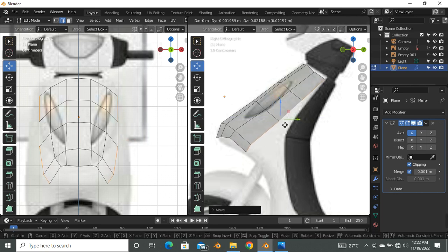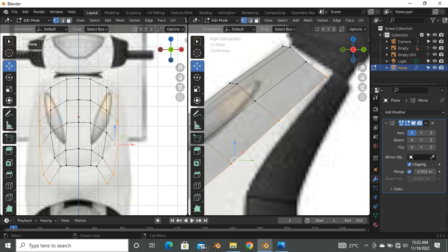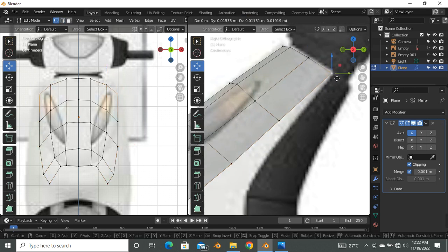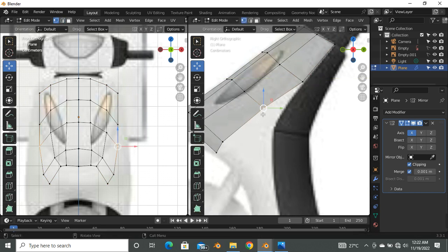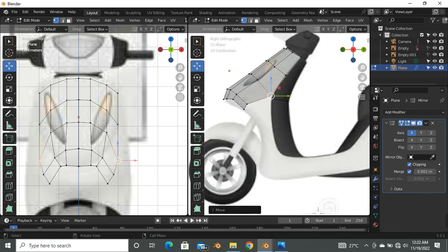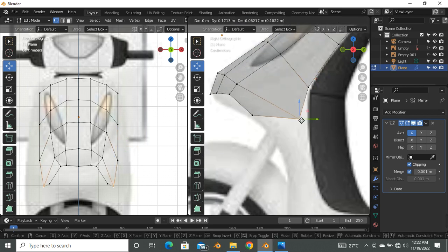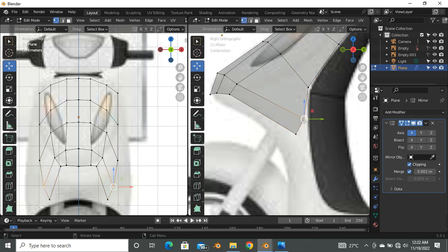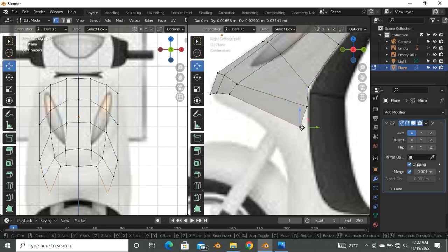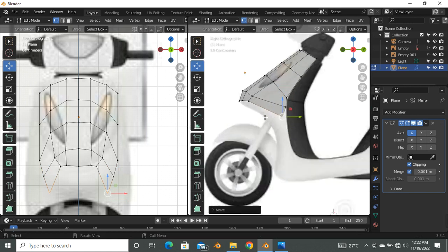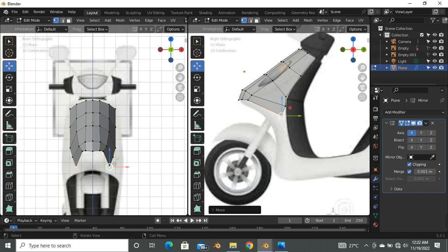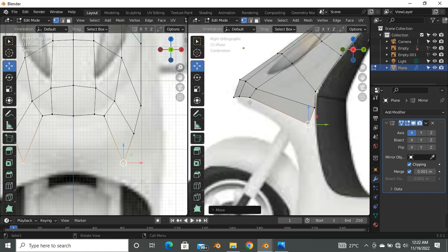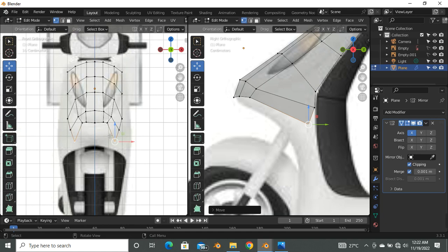and bring downwards. I can say 1 for my vector selection to just position these vertices at the right position. So I can bring this guy to this point, bring this guy to this point, and also bring this guy to this point. I don't want to go that far. I say Alt Z and see what we're having. So I think we're beginning to get something new.